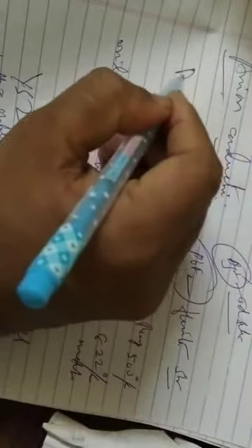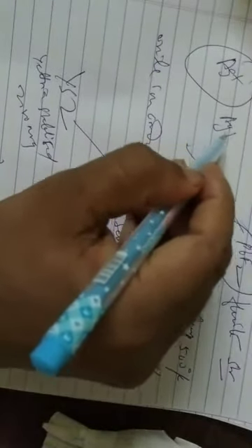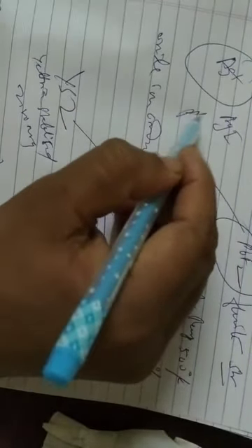So I think this is more than sufficient, and we have learned anionic conduction here. These are very useful, with most applications in sensors and fuel cells. We have learned about Ag+ ion conduction in AgI, with the phase diagram and BCC structure and how the Ag+ ions move. We also saw the composition phase diagram of silver iodide doped with rubidium iodide and how the conduction increases.